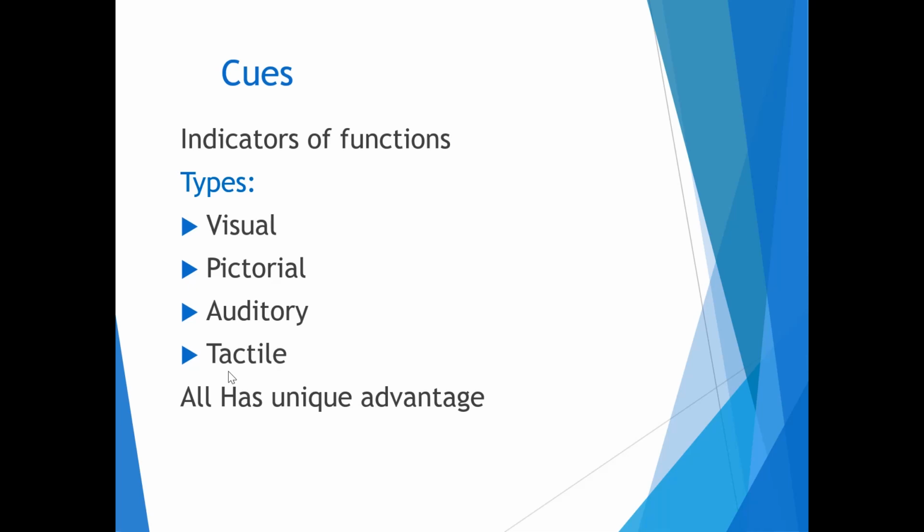Lamps give active visual cues. They can indicate whether a function is active, the mode of operation, and warnings. Many products use a small LED to signal when power is on. This cue is important when someone is trying to diagnose a malfunction. Using too many lamps can hide a particular event because human senses accommodate to multiple conditions that are similar.